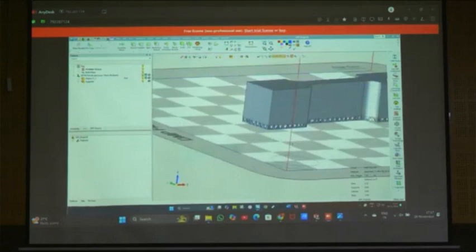Again, if you change the position also, you need to do the slicing again. We didn't change the position, but we have changed the support type, right? So again we need to calculate slices. The same story will happen: calculate slices and scanning parameters, again slicing viewer. But usually we cannot go for a one sample print; we can fill the build. Since we have less memory on the laptop, I did it like this. But there we can see actually.